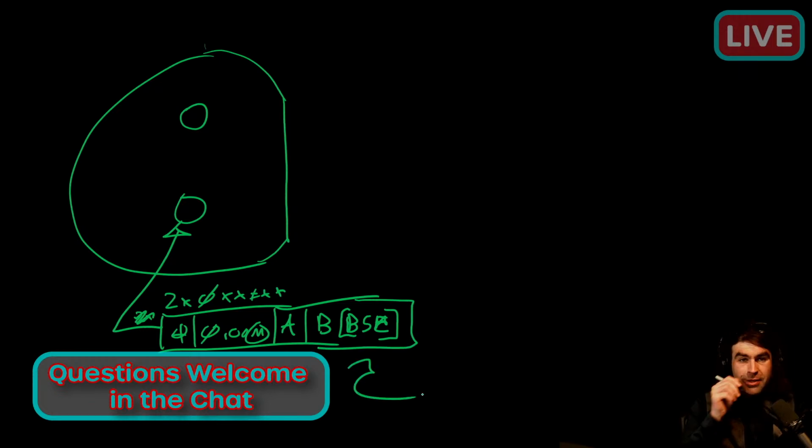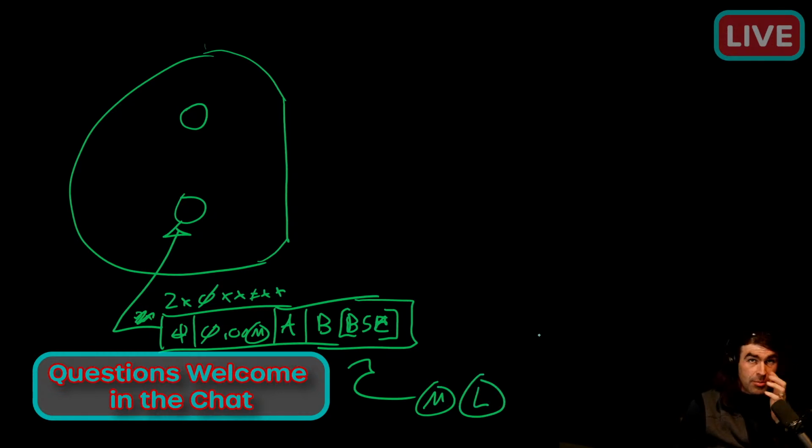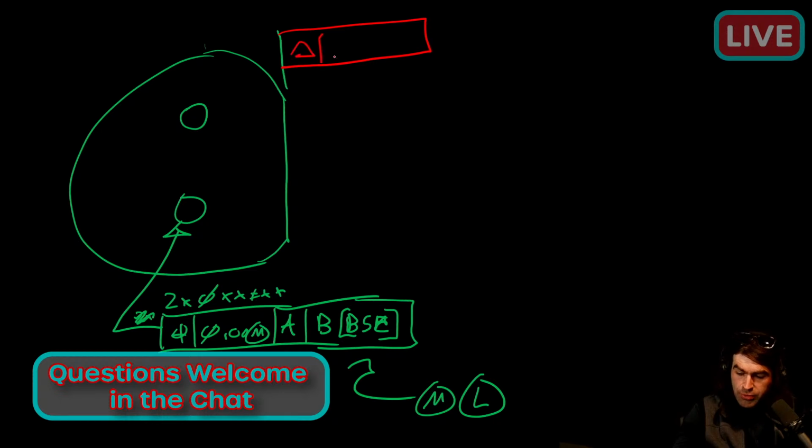So the question was, what in the world does this mean when you have capital B, SC hanging out with your datum references? Well, it means something analogous to saying M or L. And the way it's typically set up is that you would have a profile, right?